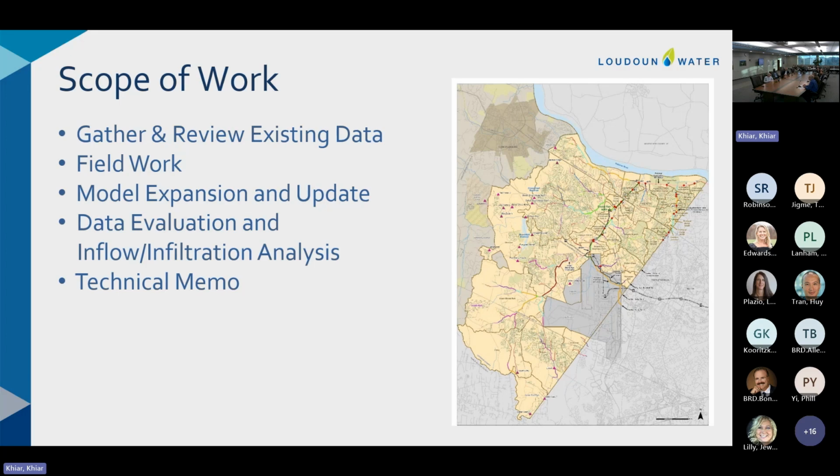For the data evaluation and inflow and infiltration analysis, this is related to the flow monitoring that we've begun, and really this portion will be disaggregating that data, trying to establish what our base flow is, what our groundwater infiltration is, the impact of rainfall on our system, and we will use that data to then calibrate the model. So this is a very important step because we want the model to accurately reflect the response of the system.